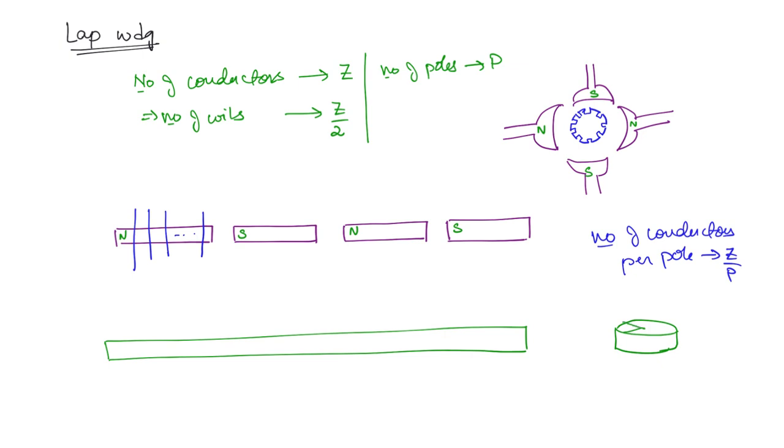There are going to be various segments, and each of these segments is separated by insulating materials. That commutator, which is in a round shape, we are also representing in a flat shape. So this is one commutator segment, this is the insulating material, and once again you have another segment and so on. Now if this first conductor is connected to this commutator segment, then the other side of it, let us say, is connected here. Which commutator segment will it be connected to? The next commutator segment.